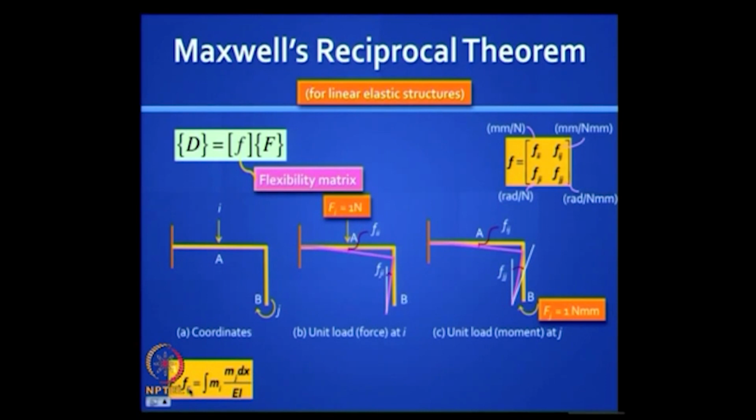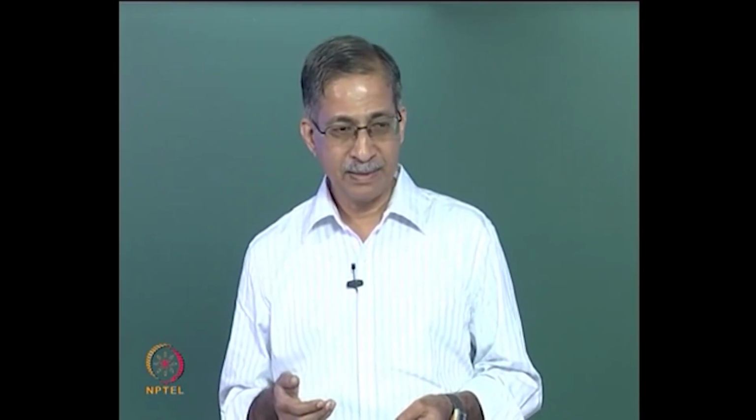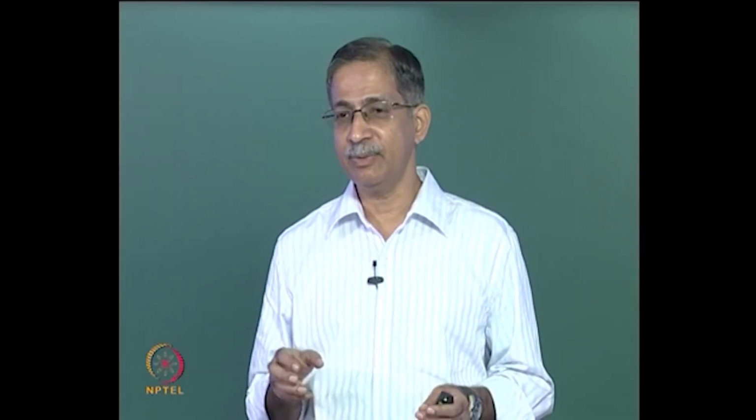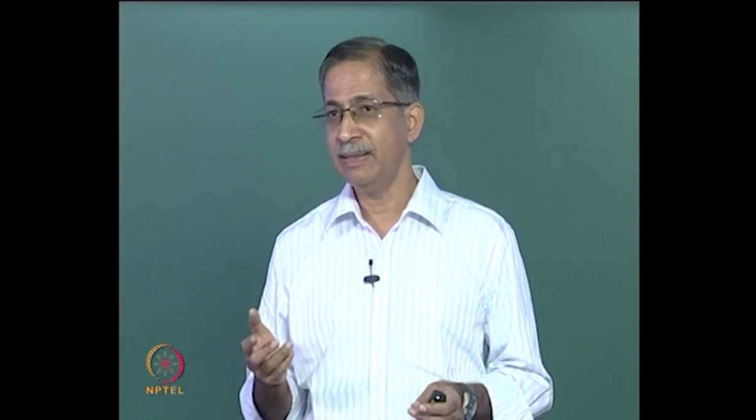This is force, this is displacement, and the internal work is, the units Mi refers to the bending moment anywhere in that frame caused by Fi equal to 1, so that is the force field, and the other one is the elemental rotation Mj dx by EI. Now this we know is true, whether you have elastic behavior or not in general, but to get the curvatures we are using elastic behavior, that is why EI comes in the denominator.